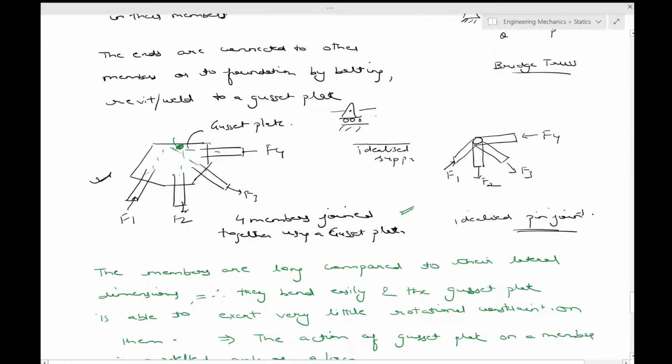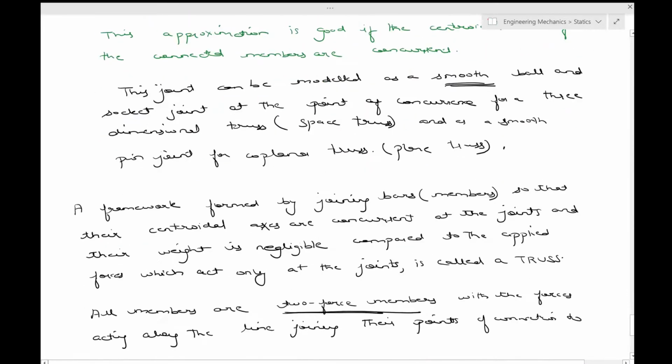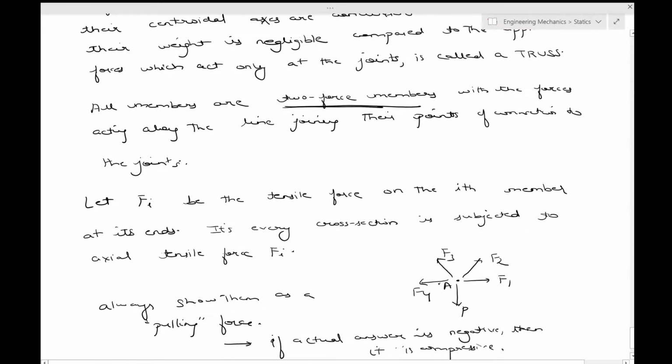It offers no resistance. It does not allow a rotation. It does not allow movement in the y direction. So it can freely slide on this x-axis. Similarly, you can have supports like this, or you can have this sort of a support. So in your examples you will see all of them and perhaps understand it much better.